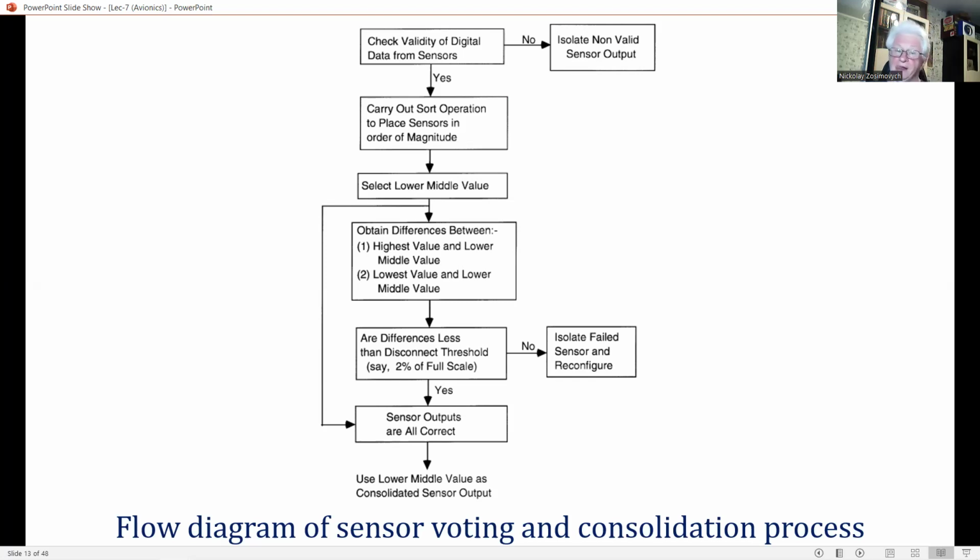The control law software is, of course, of an equally critical nature, together with the built-in test software. The control laws now being implemented in the new generation of flight control systems are of much greater complexity than in existing conventional aircraft. The high-speed microprocessors now available enable very sophisticated control laws to be implemented and the aircraft to have a higher performance and safer handling characteristics as a result.